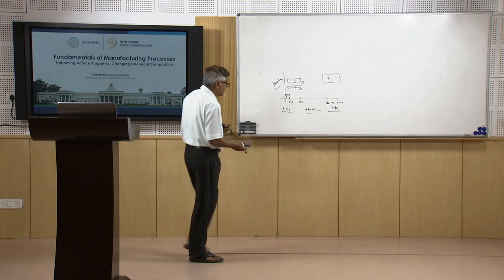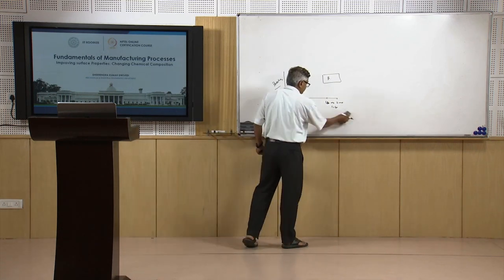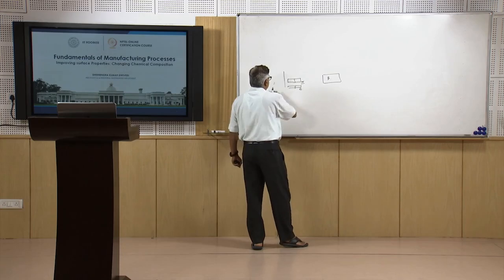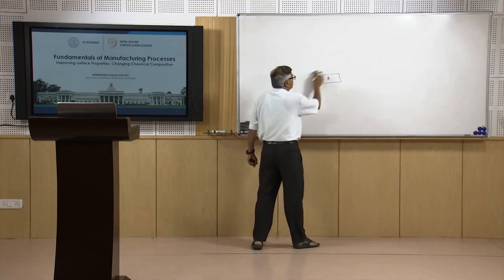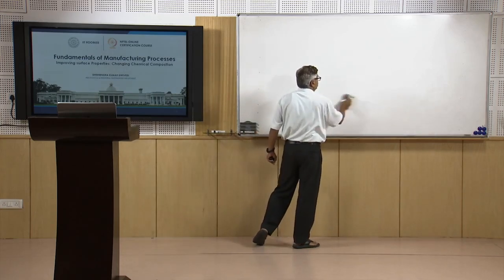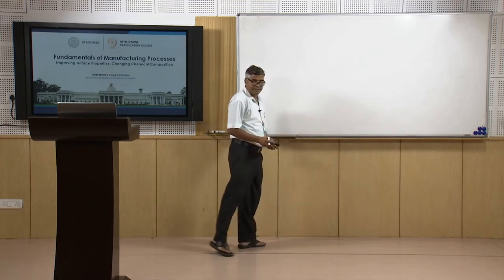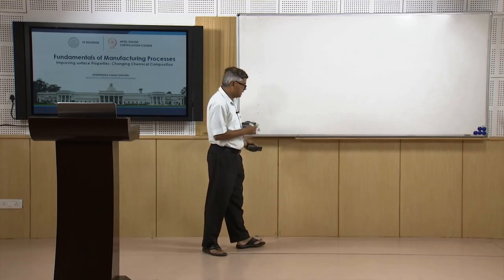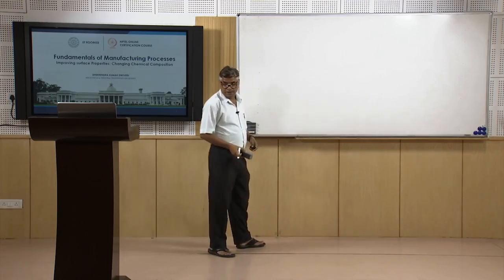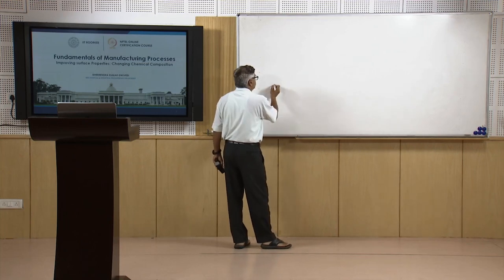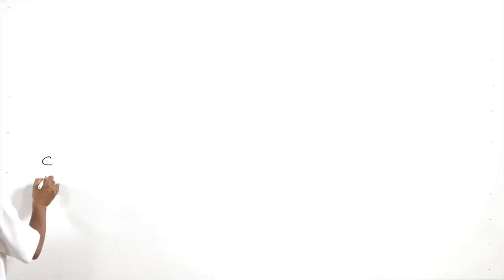So depending upon the kind of process, different hardness values can be realized, and accordingly we need to select the suitable process. So the functionality or property requirement as well as the design of the component affects the selection of the suitable process. Now we will see the general approach in all these processes, whether it is carburizing, nitriding or boronizing.